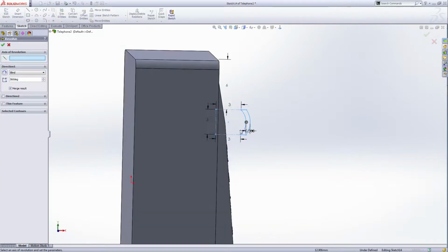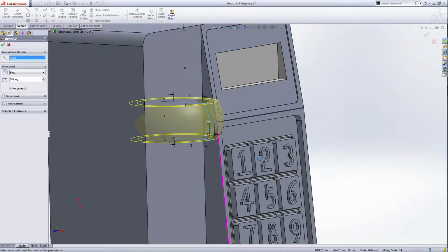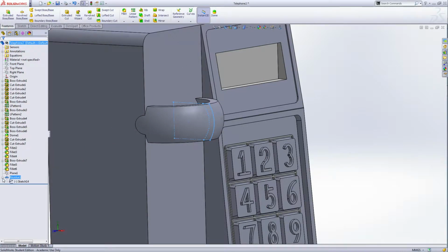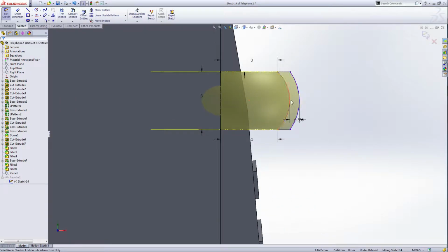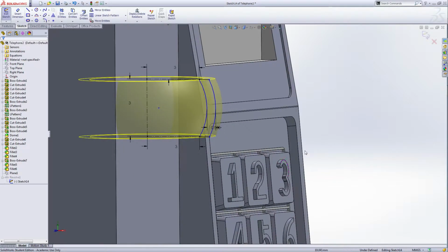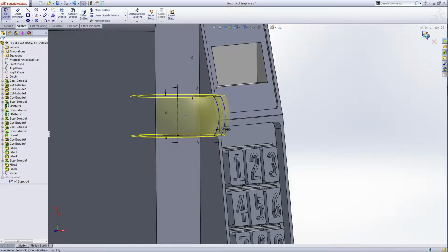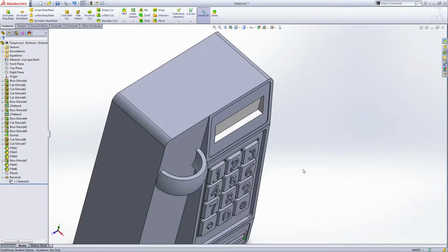Now I'm gonna do the revolve thing. So this is a closed feature. For the axis of revolve, I'm gonna select this one, because it's gonna revolve. See here, the yellow part, this is gonna revolve outside. So I just green check first, and then click here and edit the sketch. Because this part is bigger, I'm gonna make it inside a little bit. Okay, in this way, all these revolved parts are inside, so I want to leave it this way. Okay, green check. Now the whole thing is inside, and we only need this half.